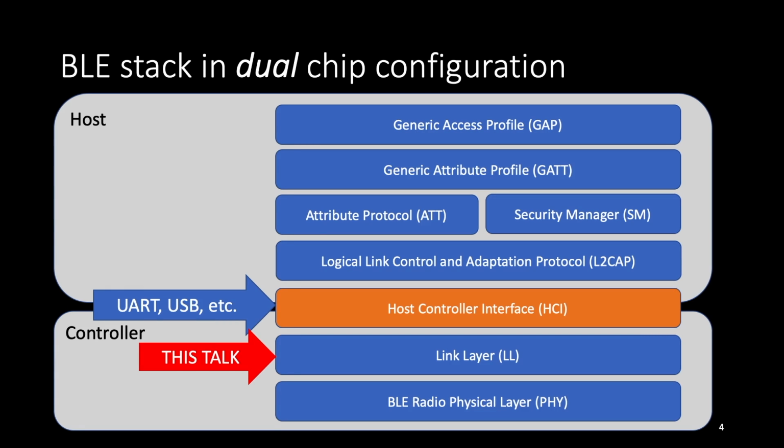Today I'm going to talk mainly about BLE because that's what I have been focused on recently. Here is the BLE stack, and there are many protocols. For the dual chip configuration, these protocols belong to the host, and these two protocols belong to the BLE controller. The specification defines how the host controller interface should be implemented.